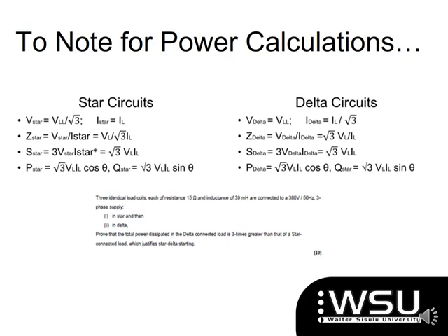So your power being P, all right? You go through the steps. You don't have to work out VAB, VBC, VCA like most of the guys that had this question went and did. Because why? You've got a balanced load. So therefore, you only need to work out on one phase, and you know you can either multiply by 3 or just use a square root of 3. And you've got your answer that would be for your 3-phase circuit.